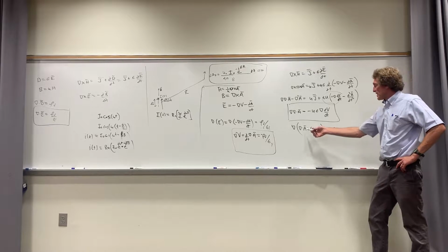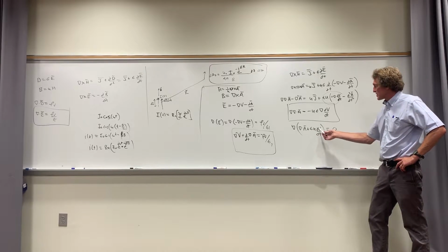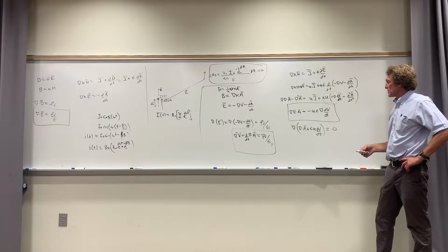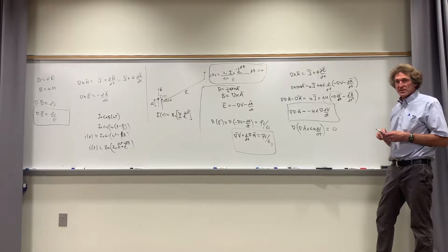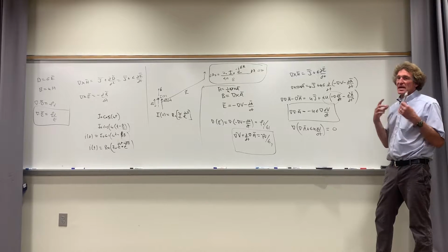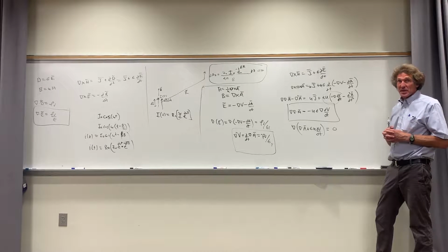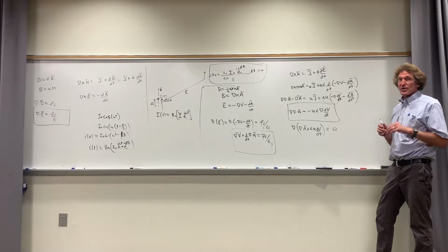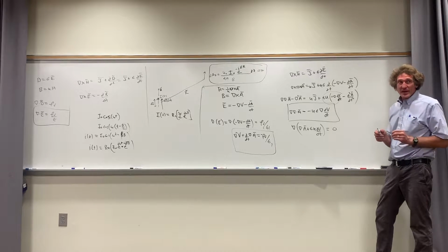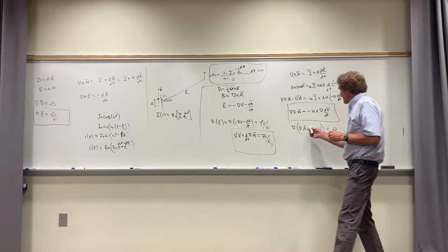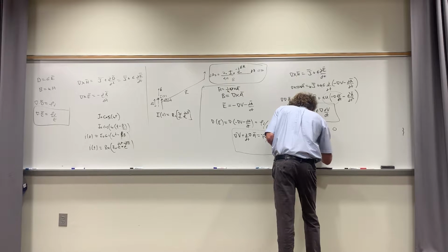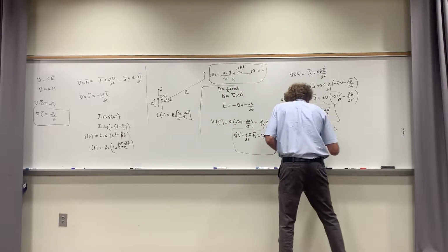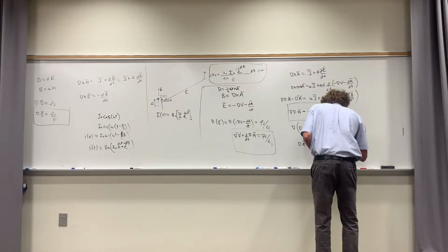Now I've uniquely defined the divergence of A plus epsilon mu times dV/dt. And this is called the gauge condition. Have you heard of that in physics? When you say gauge, it really is this: you're saying you're going to define what a constant in an equation is that's buried in the equation. So I'm going to say that now the divergence of A plus epsilon mu dV/dt is equal to 0. And this is called the Lorenz gauge.